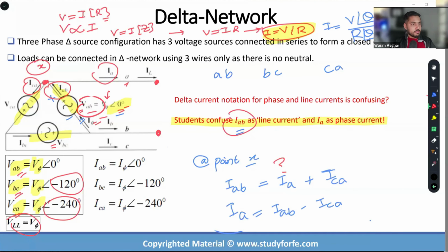Now, the interesting fact is that resistance is a simple scalar quantity always having a phase angle of 0. So this I can replace at 0 degrees. That basically tells me that my current is simply a scaled version of my voltage, such that the angle theta for the current is always equal to the angle theta of the voltage. Now, this has implications, right? Why does this have implications?